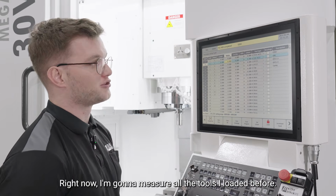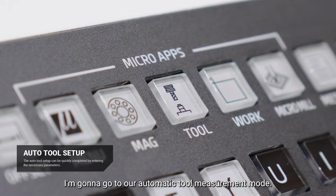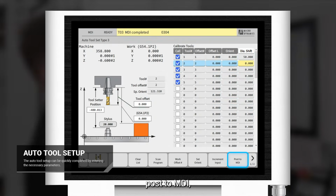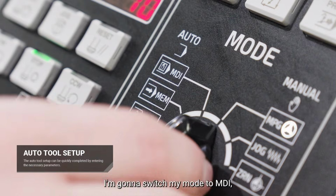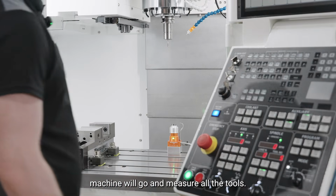Right now, I'm going to measure all the tools I loaded before. I'm going to go to our automatic tool measurement mode. I'm going to press 1, 2, 3, 4, 5. My first tool was a face mill, so I need to set the tooth diameter shift here. Then go to MDI. My knobs are all like they should be. I'm going to switch my mode to MDI, and I'm pressing cycle start. The machine will go and measure all the tools.